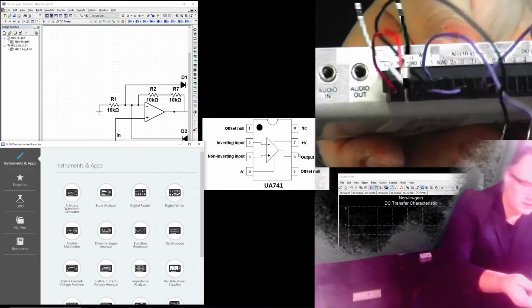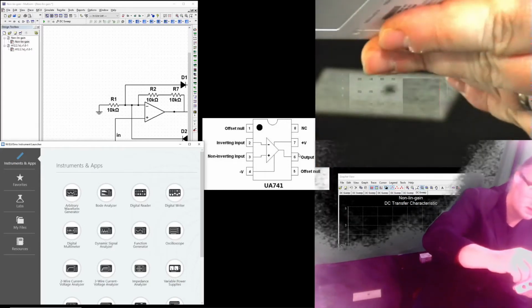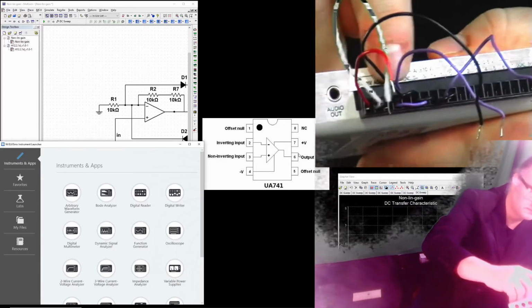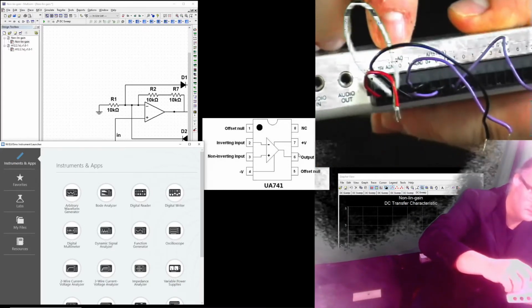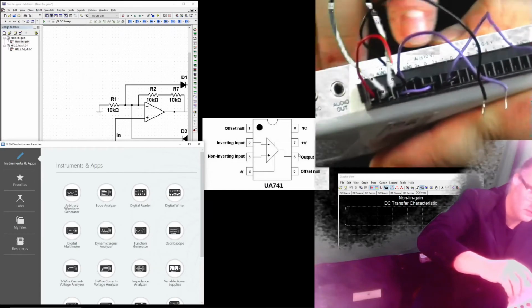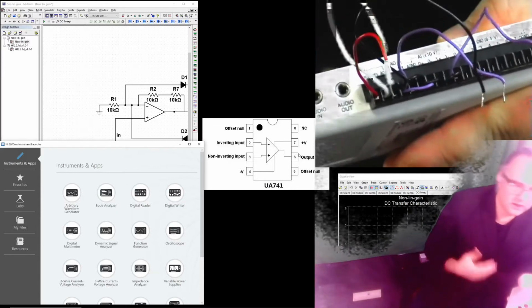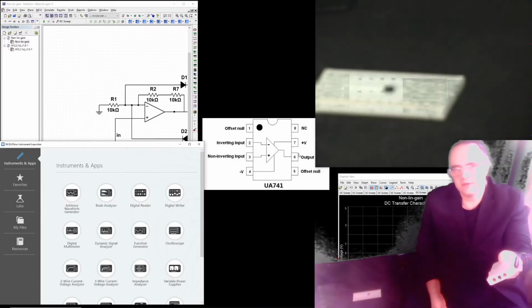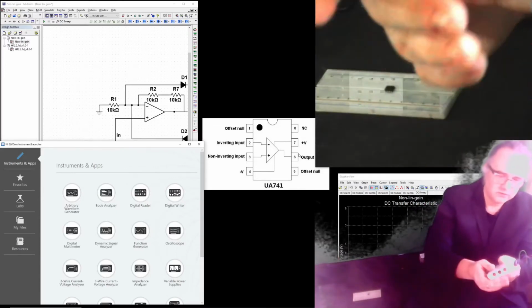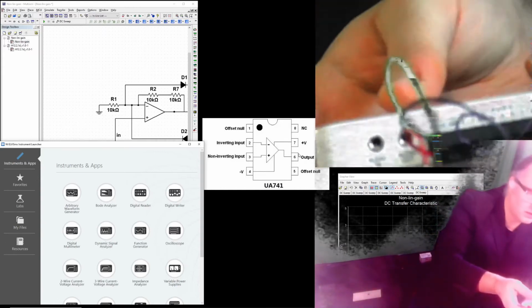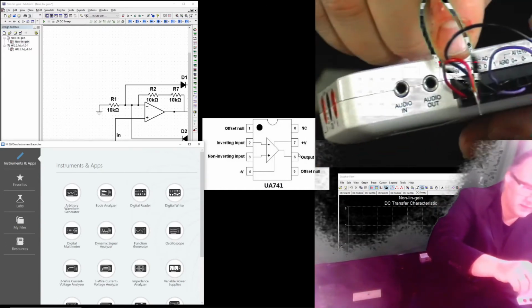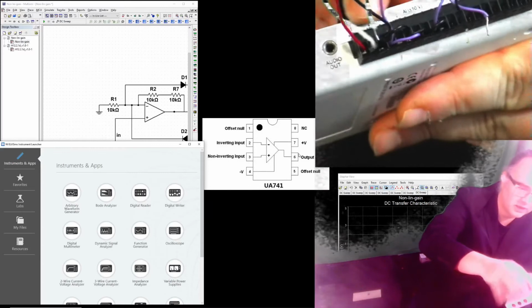In the configuration, the output is single-ended, while to measure something it's differential. And I will need single-ended measurements. So this is why I already here at the level of the MyDAQ connected a common ground.